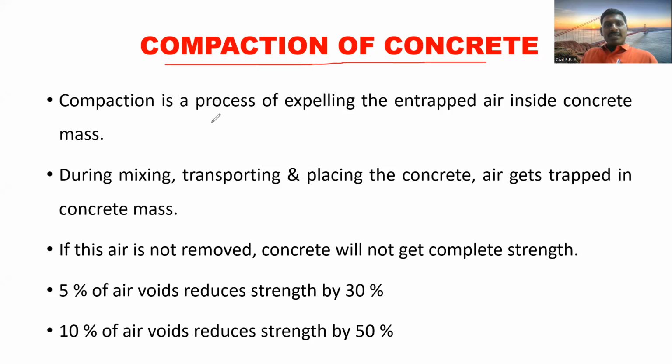Compaction of the concrete is the process of expelling the entrapped air inside the concrete mass. Whatever air is present inside the concrete, we have to expel it.